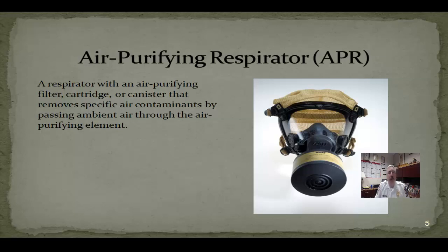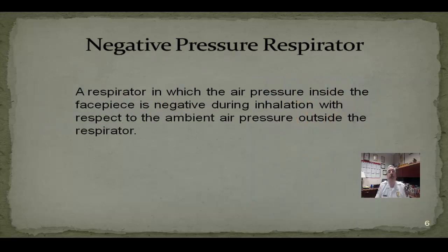This is a respirator, either full face or half face, with a cartridge, canister, or filter applied to it. With that, that filter material, as you inhale, draws the ambient air through the material, capturing those particles on that filter material. With a negative pressure respirator, as you inhale, you create that negative pressure. That negative pressure then draws ambient air through and captures the particles onto the filter material.